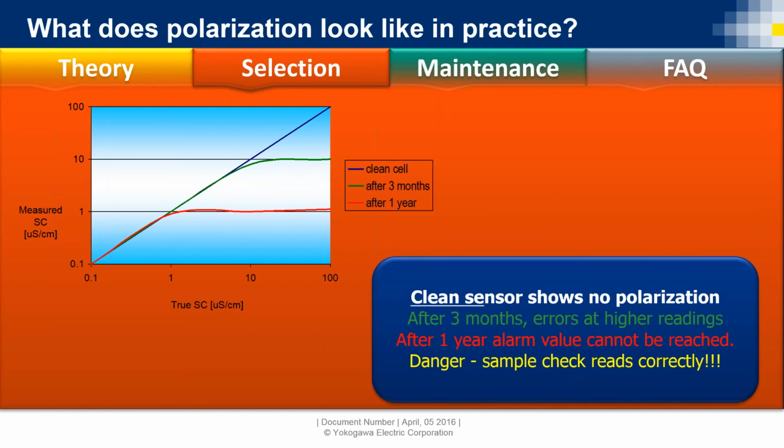So it is very common to see polarization occur that we may just think was our sensor fouling, and we just take it out, clean it, put it back in, and it starts working. Then it actually does it again. The reason why you're able to do that is these are just ions. They're just kind of friction charges on that sensor. So when you take it out, you decharge the system, you wash all those ions off of the plate, you stick it back in, and it works again.